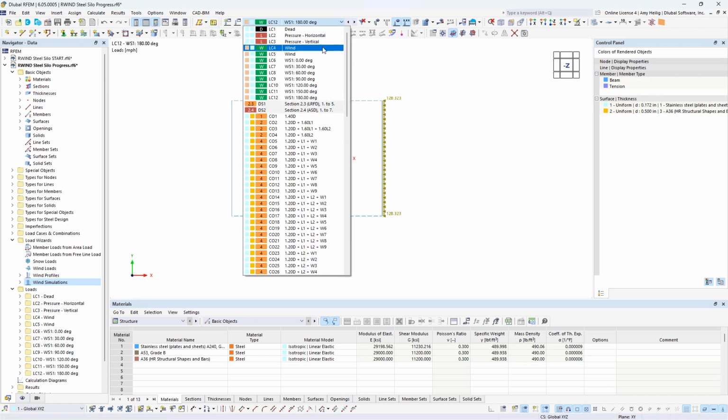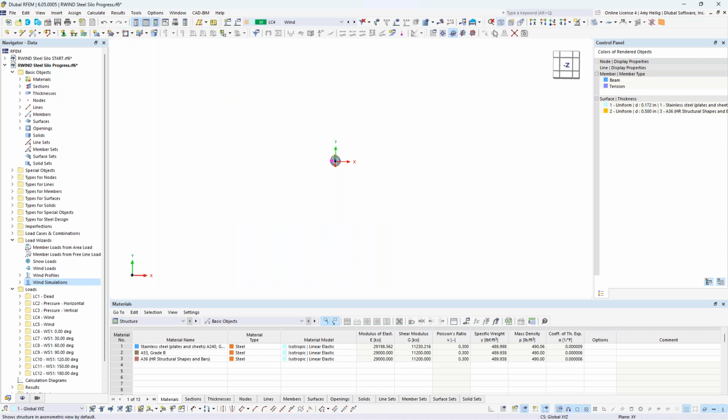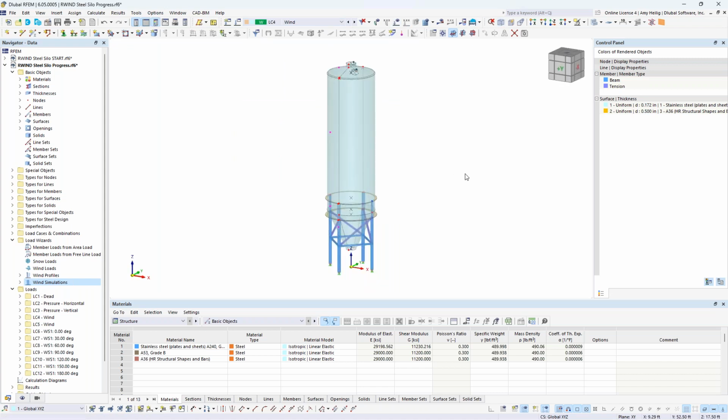So going back to our original load case here, another topic that we would like to discuss is adjacent objects. Again, the code does have some coefficients or recommendations for when we do have adjacent objects, but for anything more complex, we would perhaps want to take this into consideration in our wind directly. For my example today, I have this silo structure, and this is the structure, of course, I'm interested in designing, but perhaps there are identical silo structures placed very closely to this one that I know are going to affect my wind flow.